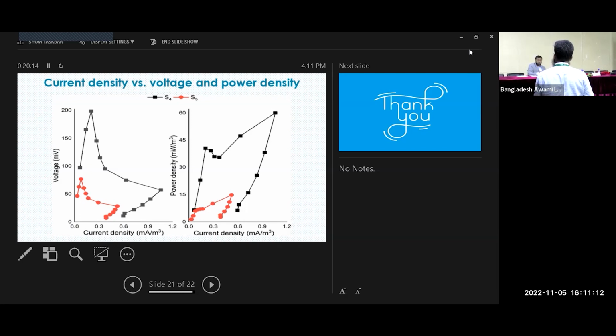You will find it in our paper. I didn't show it to reduce the content, but we have significantly reduced it, and some systems also achieved 97, 98, 99% coliform removal. That means it's a 1 log removal. Still 2 log is available in the environment. You need to understand, because in any system, you will achieve 99%. That means you will again have 1 log that you need to achieve through disinfection. And you can achieve that through a surface flow wetland.